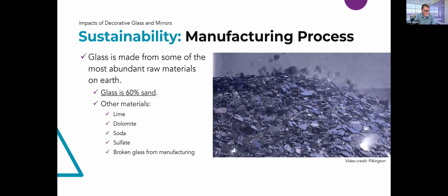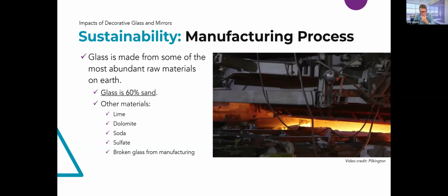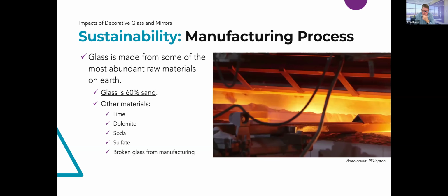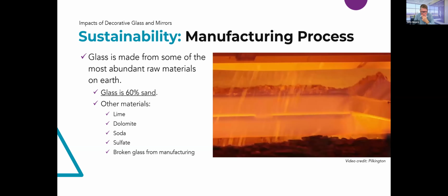Broken glass, called cullet, is recovered from the manufacturing process and then crushed before being added to the batch. This further accelerates the melting process and reduces the amount of energy required for melting by up to a fifth. All raw materials are rigorously checked to ensure the purity of the batch. It is then fed automatically into the filling end of a furnace. Natural gas, burned in preheated combustion air, then heats the batch up to 2,800 degrees Fahrenheit.